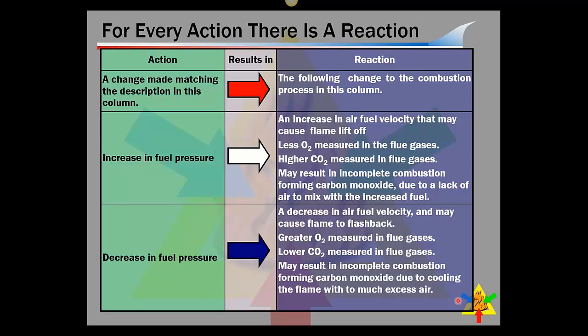Okay. Well, let's think about a water heater. Let's say we take a water heater and we put a blanket on it and we accidentally cover the intake vents. Is that going to reduce the amount of air available for that appliance to burn? Absolutely. So that's another example. There's lots of others out there. We'll move along and get you guys through this.